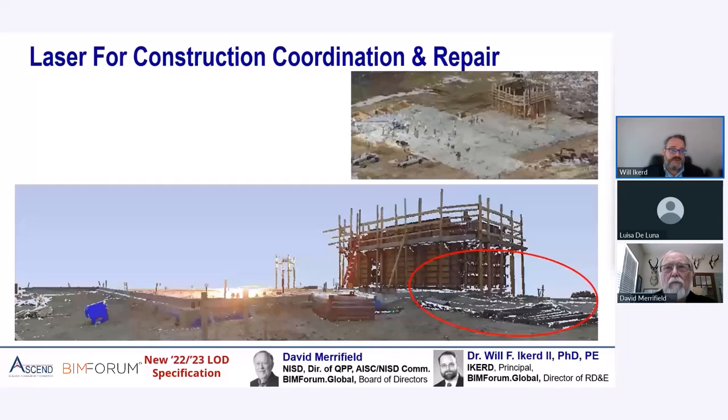And so that's why when you're dealing with as-builting and 500 model elements, you need to clarify: is the geometry based on 350 or 400 or 200 or 300? In this example, for what Dave needed to cut new openings or enlarge openings in base plates, he did not need the threads on those anchor rods. He did not need the portions of the anchor rods that are cast into the concrete. He really was concerned with the anchor rods protruding out of the concrete that he had to interface with.